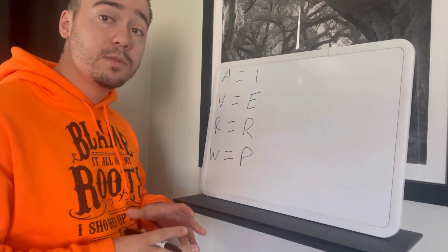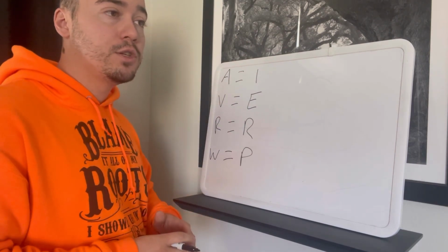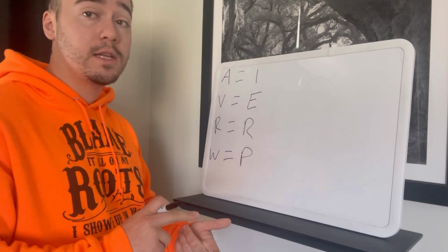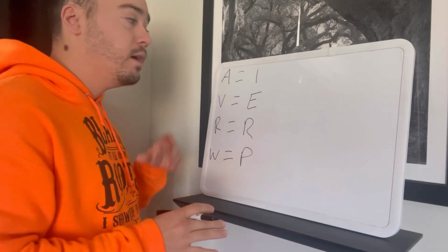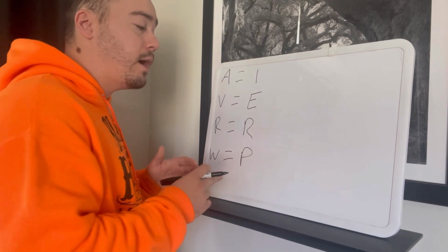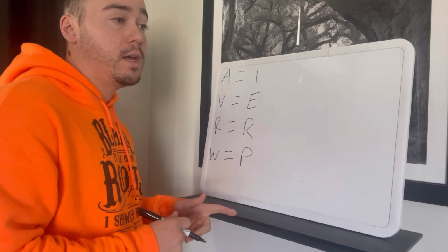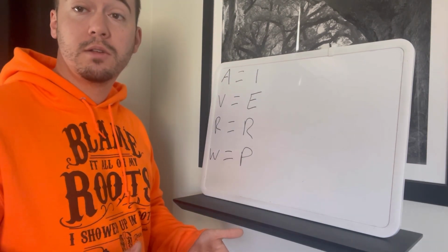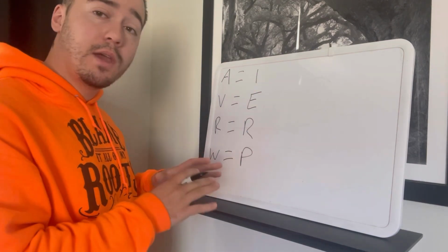Now you can use Ohm's law and the way that all these interrelate to each other to make calculations to decide what size your circuits are going to be, what size the wires are going to be in that circuit and all that. But it also helps you understand when you're measuring this kind of stuff that if you have 120 volts and let's say your resistance is 10, then you're going to be pulling 12 amps. Yeah, that sounds about right. So I'm going to show you how to do that.